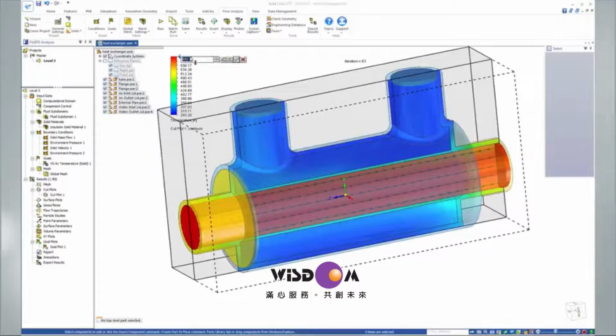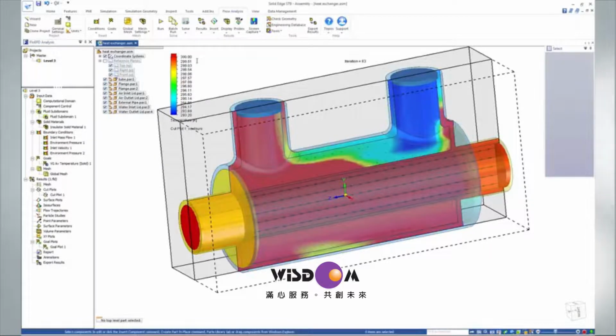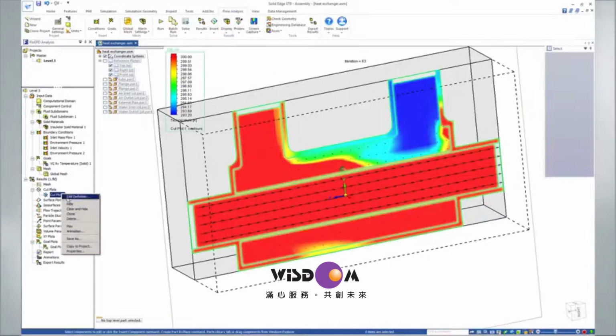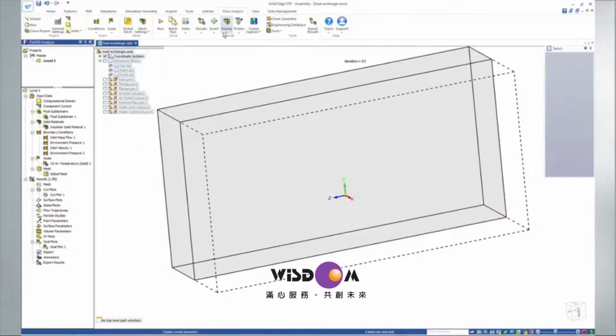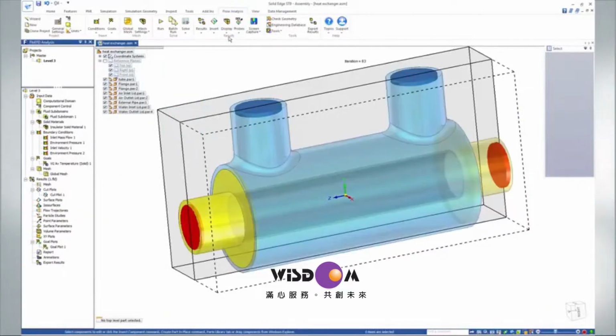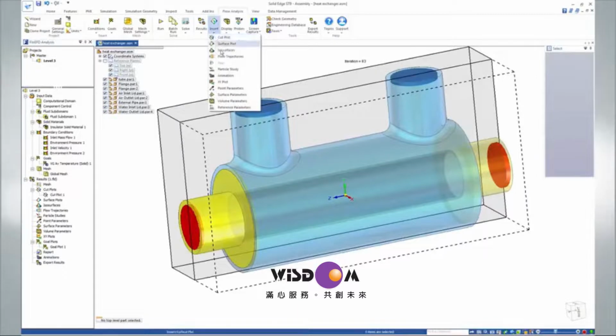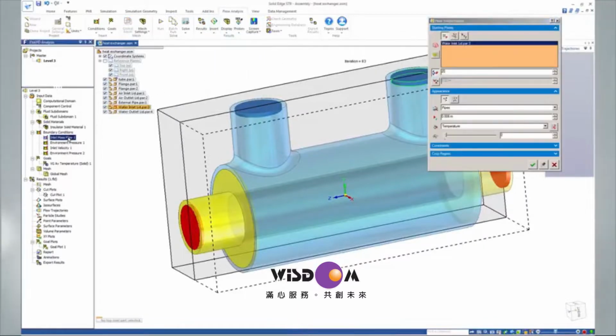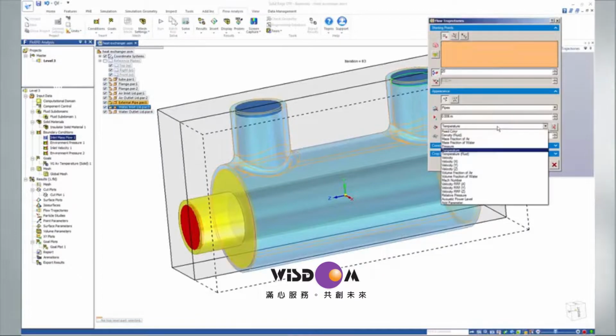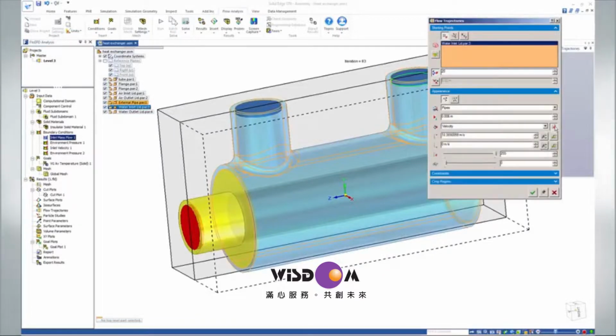We can adjust the temperature bar by clicking, for example, on the maximum value. Click the geometry icon to hide the model. We hide this plot and click on the geometry icon again and click on the flow trajectories. Select the inlet water boundary condition, change the color appearance to velocity, and adjust the maximum velocity to 0.004 meters per second.